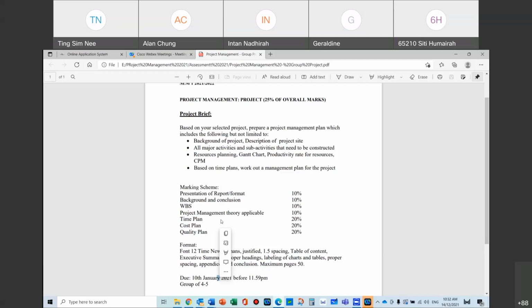If you split up in your resources list, one rate will go to the machine itself, one rate will go to the driver itself. But if you go for a package, normally you just use the rental package at 500 per day, which comes with the operator. So it will not make any difference in the Gantt chart. No matter what, it has to be driven by the operator.